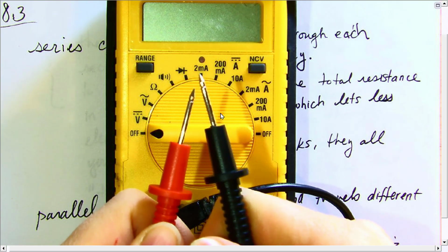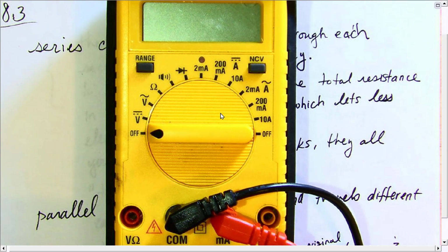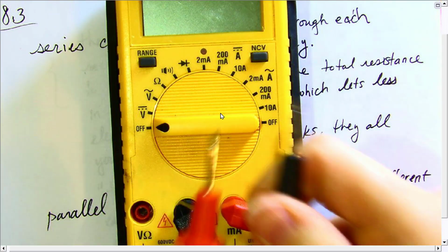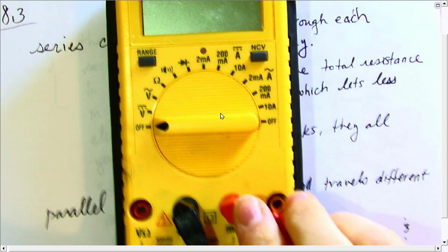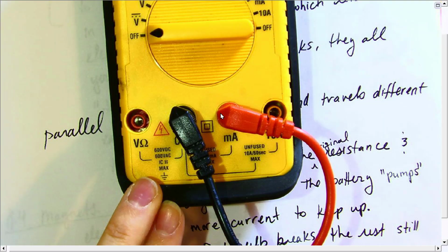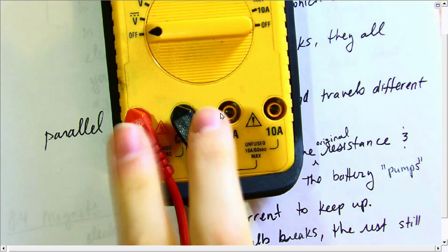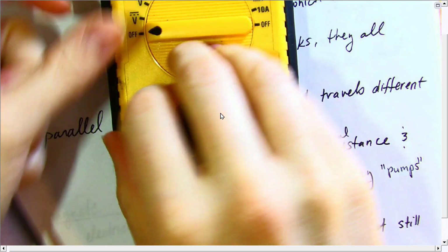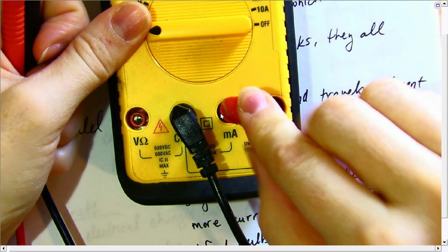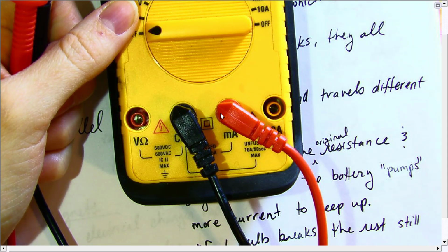I would suggest only doing that after you've had some other practice with less dangerous things though. Especially don't be sticking these into wall outlets unless you know exactly which holes your wires should be plugged into. It is okay to do that if you have them plugged in to measure voltage. It is not okay to do it if you have it plugged in to measure current, because then it will make a short circuit.